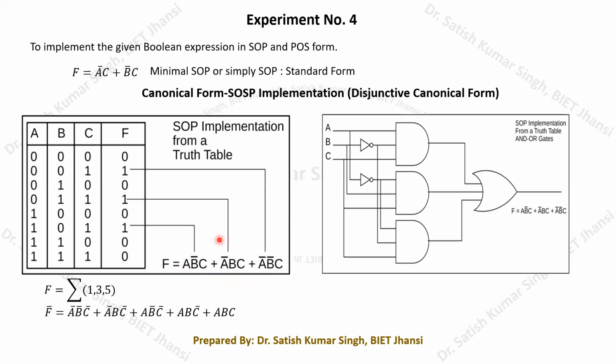So in this particular experiment, we are actually going to conduct an experiment to implement a circuit in the SOP form. You remember that we generally write SOP or POS implementation, but here we are going to implement a SOP implementation. That means the sum of standard products. It is not just a sum of products, but a sum of the standard products, or a sum of min terms. So you remember that it is a sum of min terms.